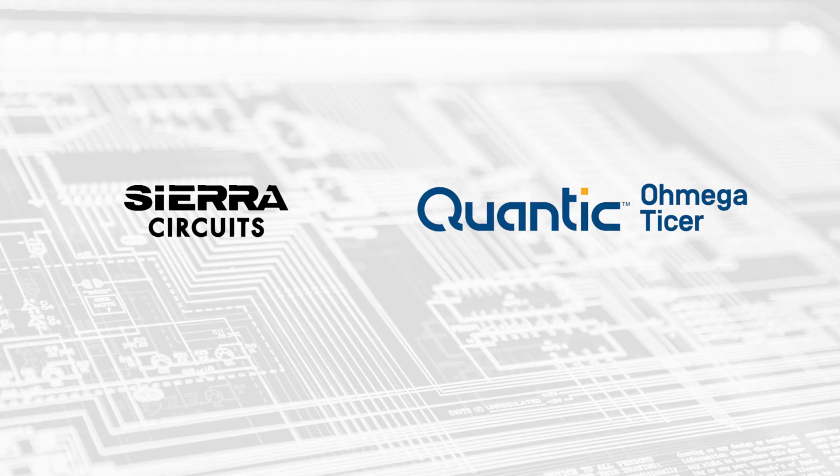It turns out we have products that have very low profile copper, and we've tested up to 40 gigahertz. The amount of additional loss you get, because that resistive layer is so thin, is fractions of a decibel per inch. So people are routing their high speed signals on those layers. In fact, we sell a lot of product to people using PTFE, Teflon-type based materials, and they're routing high speed signal traces on those layers.